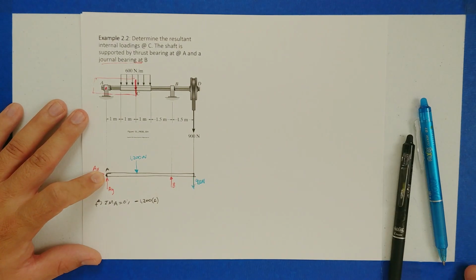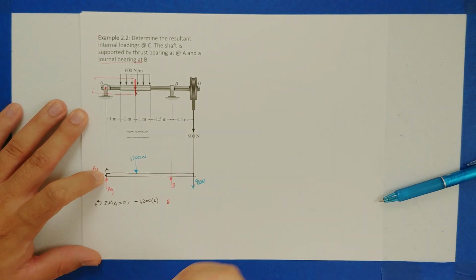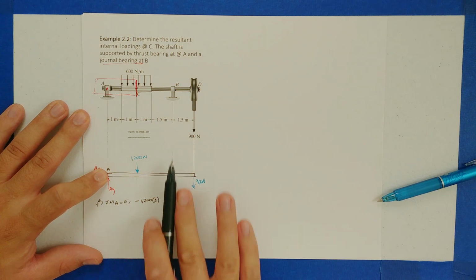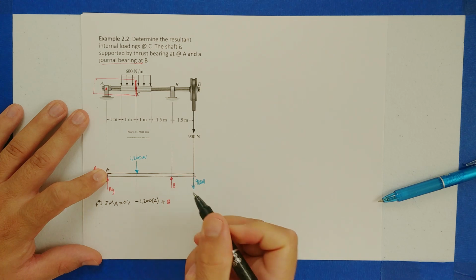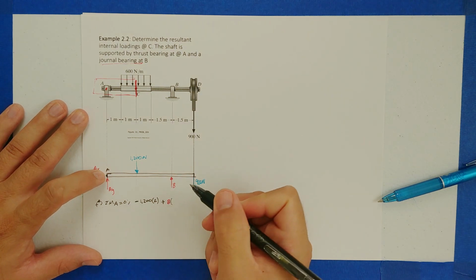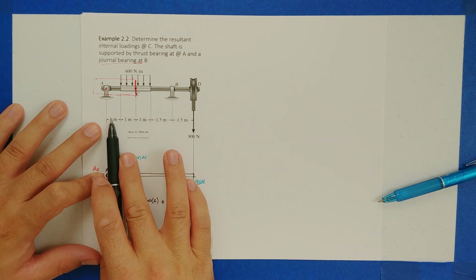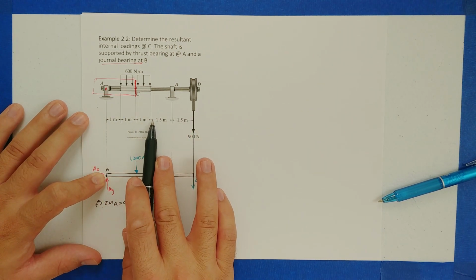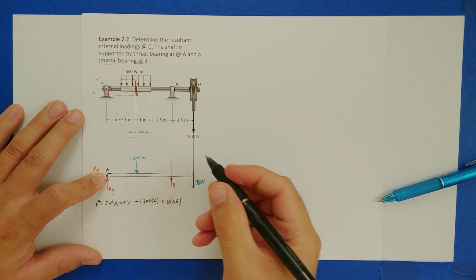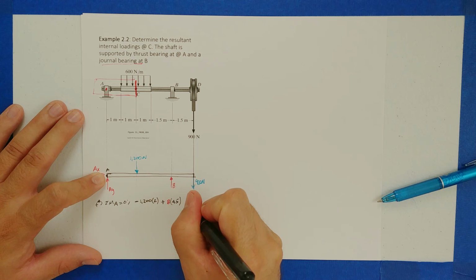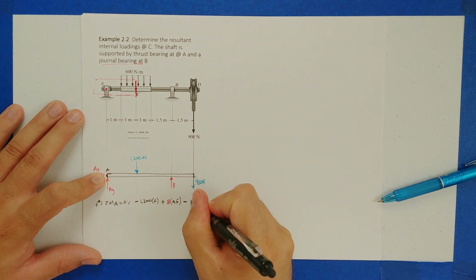Next, we have the reaction at B, which is what we're trying to solve. If I'm pinned at A and I push up over here at B, it would make the whole thing rotate counterclockwise, so that's a positive moment. The force is this B, and the distance is our distance from A to point B, so we got 1, 2, 3, 4.5 meters. And then finally, we have the 900 Newton load. It's pointing down, so it's going to make it rotate clockwise, so it's a negative moment.